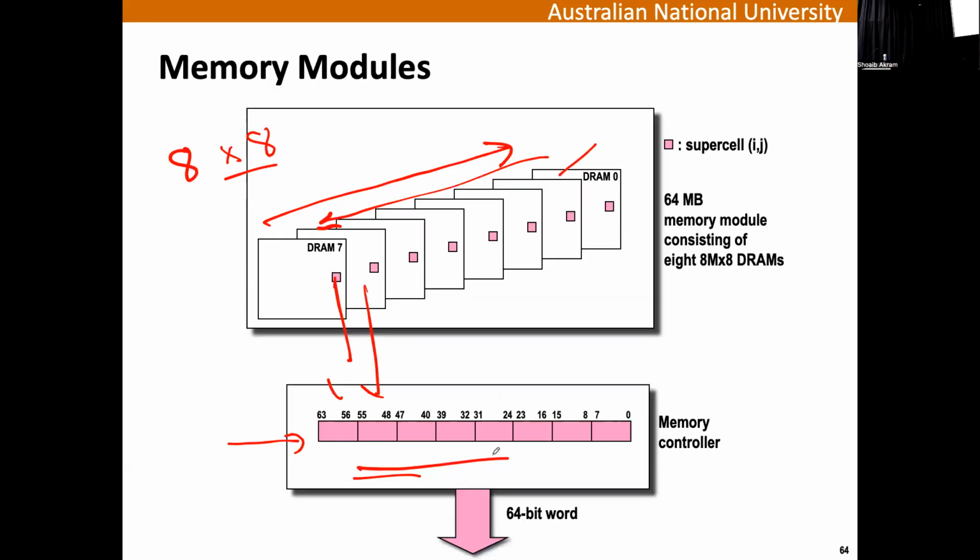Okay, so we're done with device characteristics. From now on, in the labs and in the course, we will be using these ideas: locality of reference, spatial locality, temporal locality. You should look at the program and say, hey, I can do this rearrangement to exploit more spatial or temporal locality. You should be able to look at the program and say, hey, there are a lot of random accesses when I'm accessing an IO device or a storage device, when I'm accessing a file. I can do something really smart to turn all of these into sequential accesses. Okay, and we will keep exploring these ideas as we go. All right, thank you.